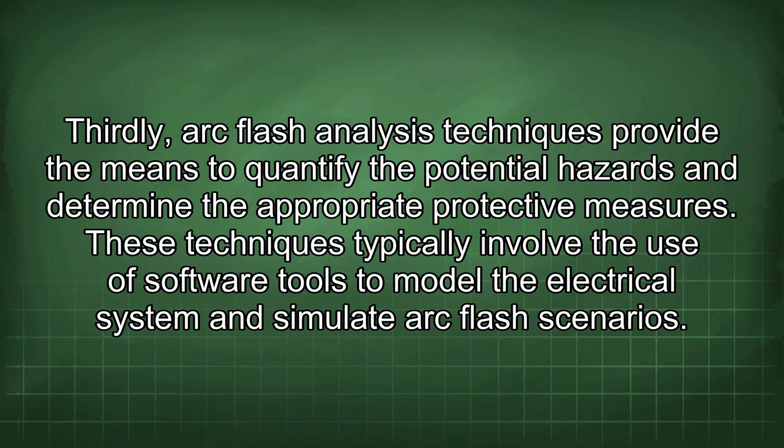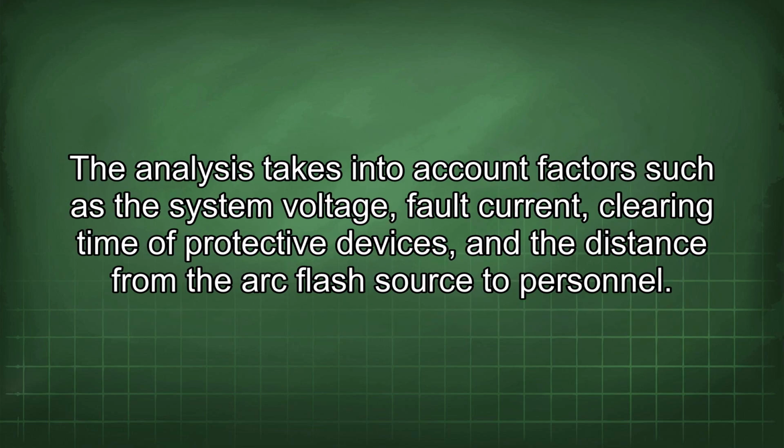Thirdly, arc flash analysis techniques provide the means to quantify the potential hazards and determine the appropriate protective measures. These techniques typically involve the use of software tools to model the electrical system and simulate arc flash scenarios. The analysis takes into account factors such as the system voltage, fault current, clearing time of protective devices, and the distance from the arc flash source to personnel.